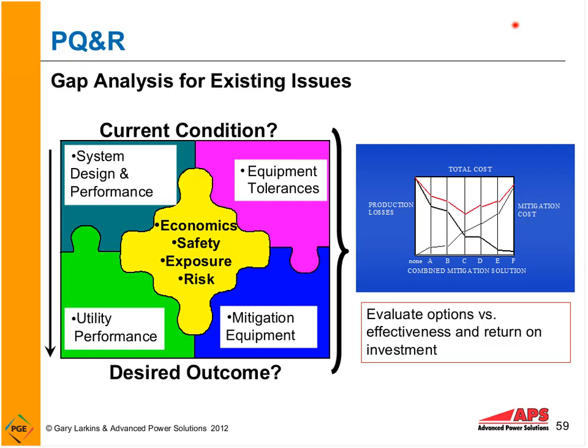Yes, they had an event. They weren't properly protected by surge protection initially. It caused damage. They needed to replace that equipment. But the ongoing power issue was not related to power quality. It was the fact that they needed to clean out those boards and start over. It was originally a power quality issue, but the ongoing events were not power quality issues because the proper equipment had been put in place.